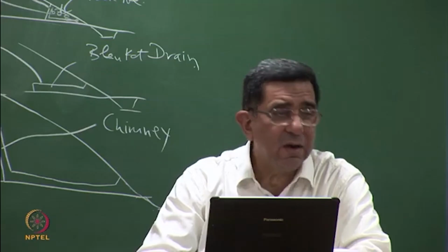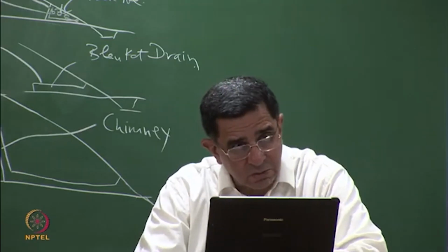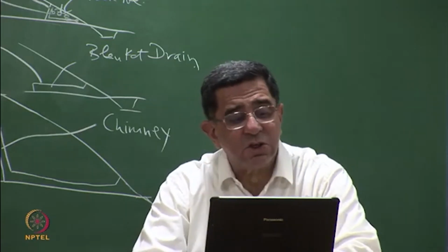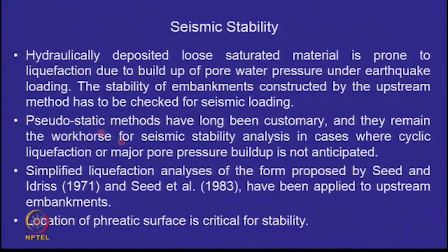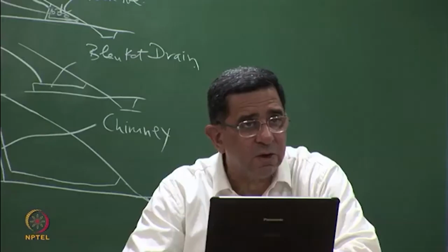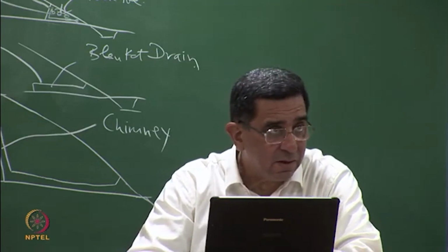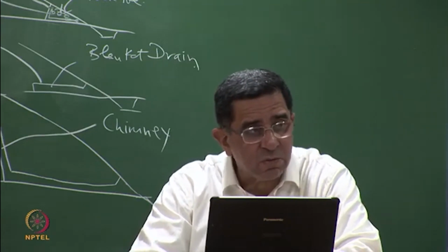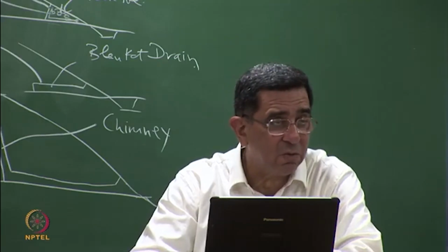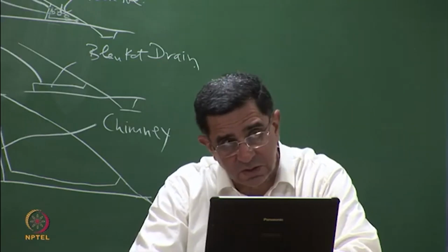1.05, 1.1. So both these conditions should be met. But the third thing that you have to analyze is the liquefaction analysis. You can use the Seed and Idriss approach of finding whether your tailings will liquefy, and if they will liquefy, to what depth, because your embankment may be stable, but during earthquakes you may have the possibility of liquefaction. So this has to be investigated in detail.